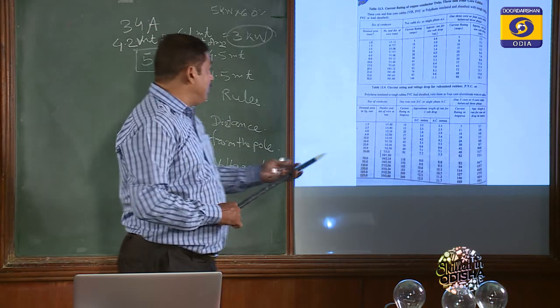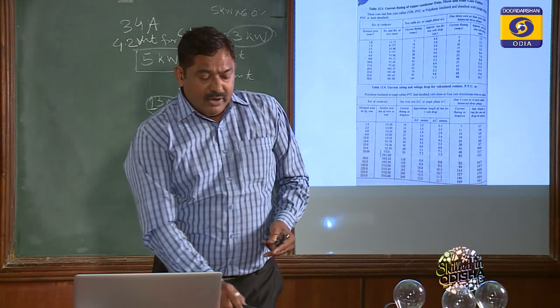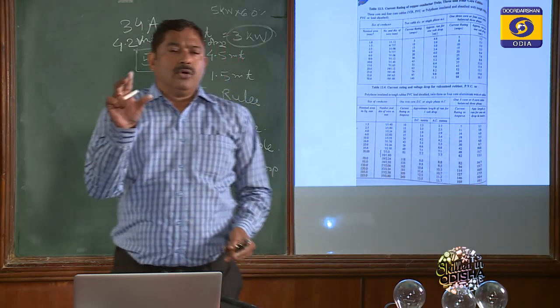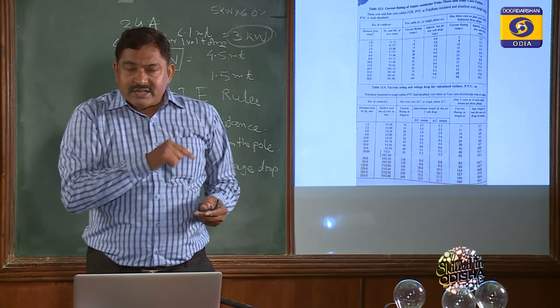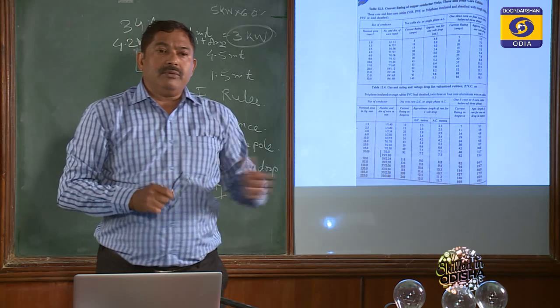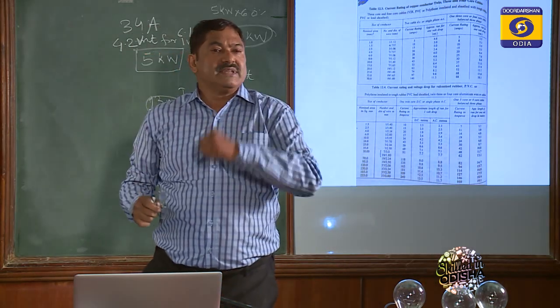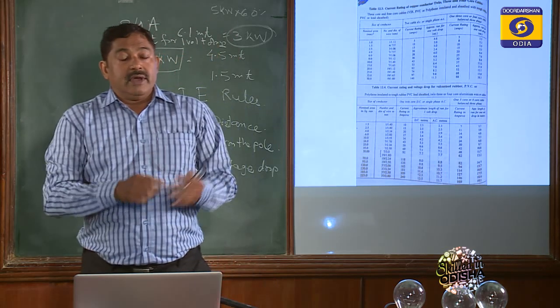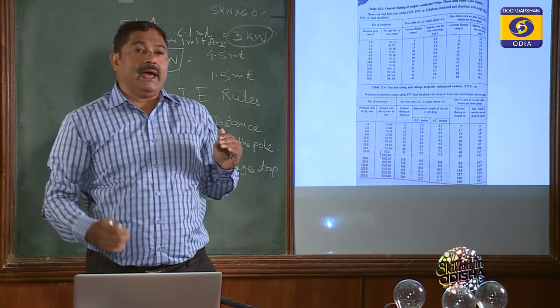We have no problem, and we have to always keep in mind that frequently in the household the bulb glows dim because of this particular reason. When we draw the service line, when we calculate 13 ampere, we give a 13 ampere service line. In that case, 13 ampere it can stand, but voltage drop will be there.